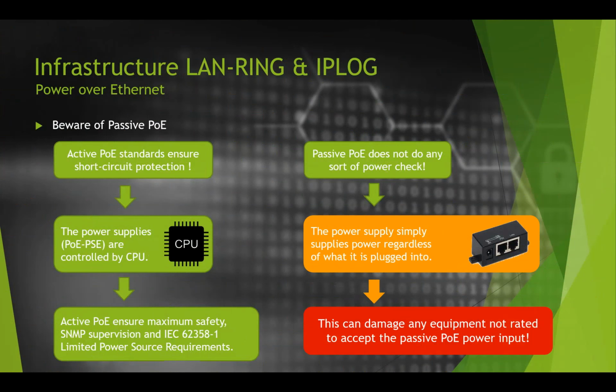Please do not confuse active PoE standards with passive PoE. Passive PoE solutions are usually cheaper, but do not offer any verification of the compatibility of the connected load. If the connected load is not compatible with passive PoE, it can easily be destroyed and, in extreme cases, even cause a fire. Active PoE works quite differently.